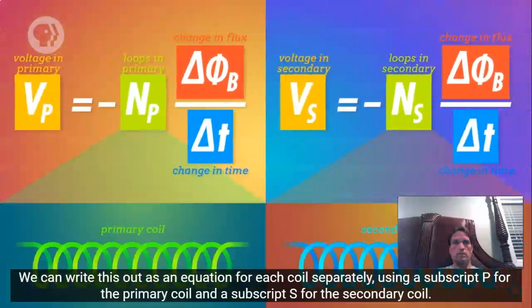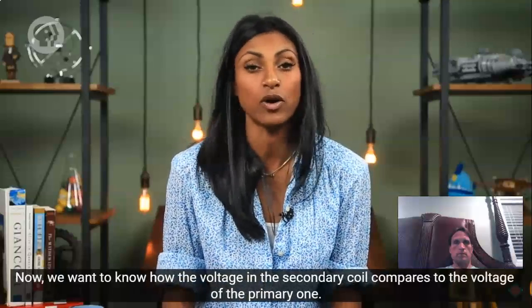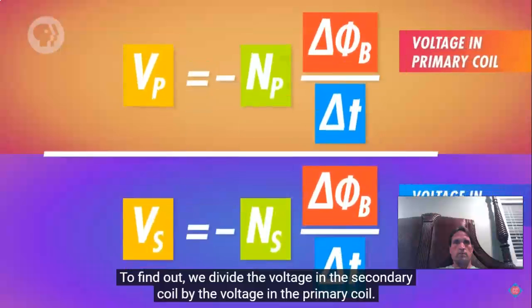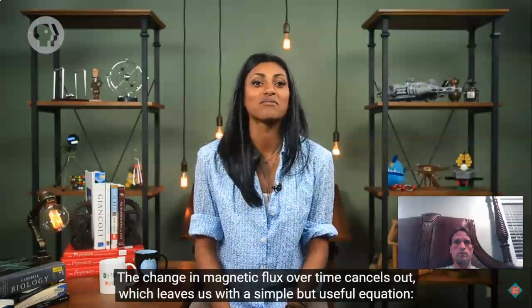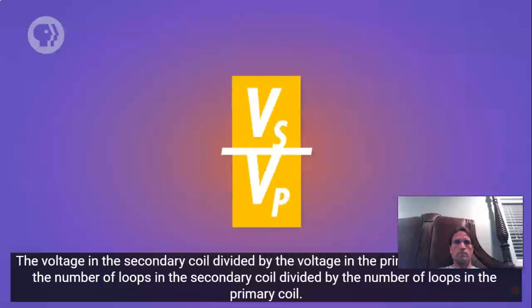We can write this out as an equation for each coil separately, using a subscript P for the primary coil and a subscript S for the secondary coil. Now, we want to know how the voltage in the secondary coil compares to the voltage of the primary one. To find out, we divide the voltage in the secondary coil by the voltage in the primary coil. The change in magnetic flux over time cancels out, which leaves us with a simple but useful equation.